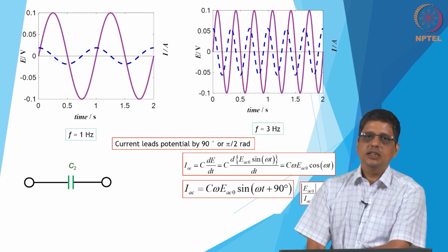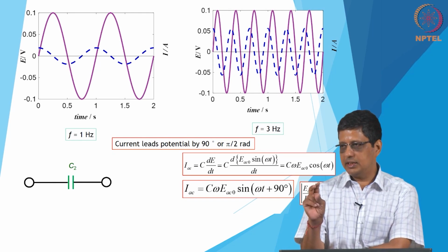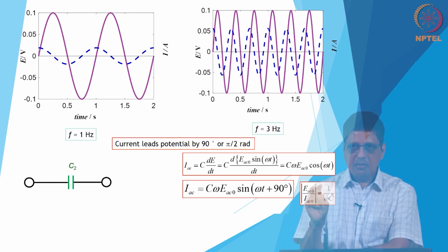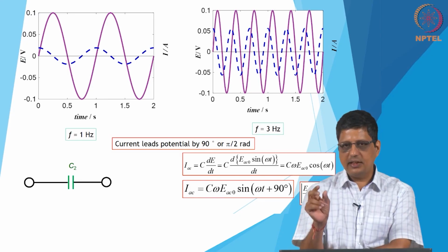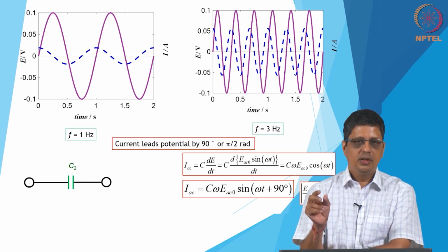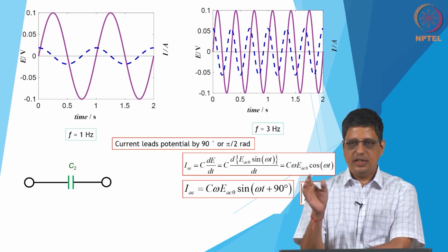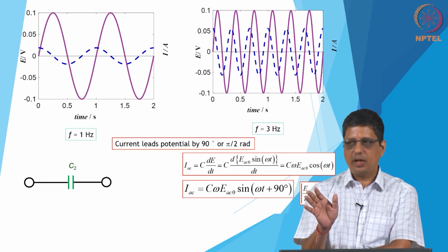Normally resistance is something where we say potential divided by the current will give you the resistance. Impedance is also a potential divided by the current, but you also have to know the phase. So, it has a magnitude and a phase. In case of a resistor the phase is 0. In case of a capacitor, an inductor, or in general a reactance, you have to expect that the phase may or may not be 0.